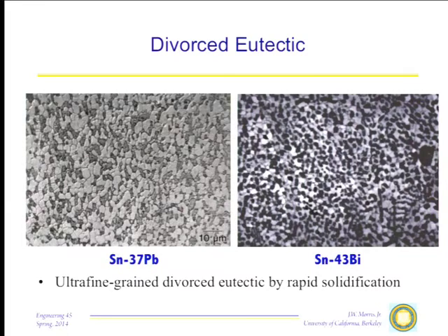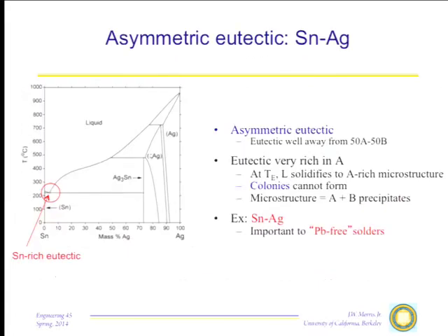So this lead-tin eutectic, which has a low melting point, is relatively inexpensive, has a very good microstructure, and would cool quickly, was the great white rat of the entire electronics industry until people decided they didn't like lead anymore and caused something of a revolution. The revolution has produced something of a problem, because what we've gone to in lead-free solders is silver-tin or silver-copper-tin, silver-copper. All of these systems have a very off-symmetric eutectic.